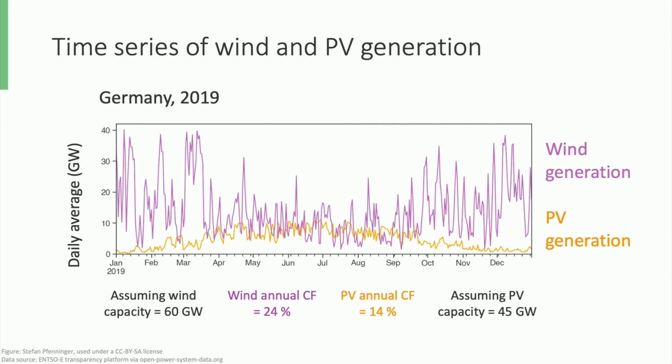How do we work with the capacity factor? Well, let's add German PV generation. The first thing you notice is that the absolute amount of electricity coming out of Germany's PV systems is quite a lot less than that coming out of wind farms. We can calculate the annual capacity factor for PV, same as before, and we get an annual average CF of about 11%.